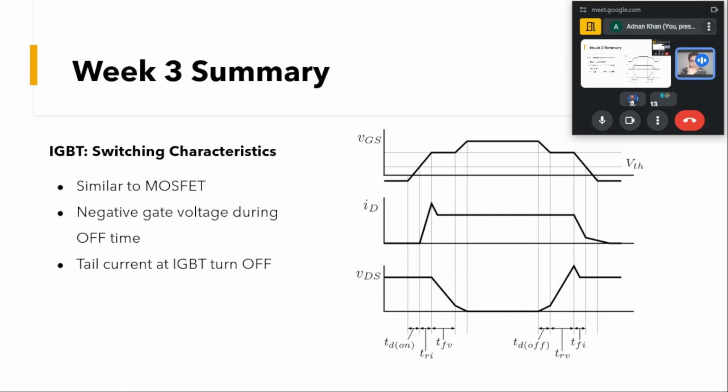When the current starts to flow, before that some voltage is being blocked across the device. As soon as we apply the gate voltage, if you go into the physics, some channel is formed in the IGBT, the current starts to flow, and after that VDS starts to drop.